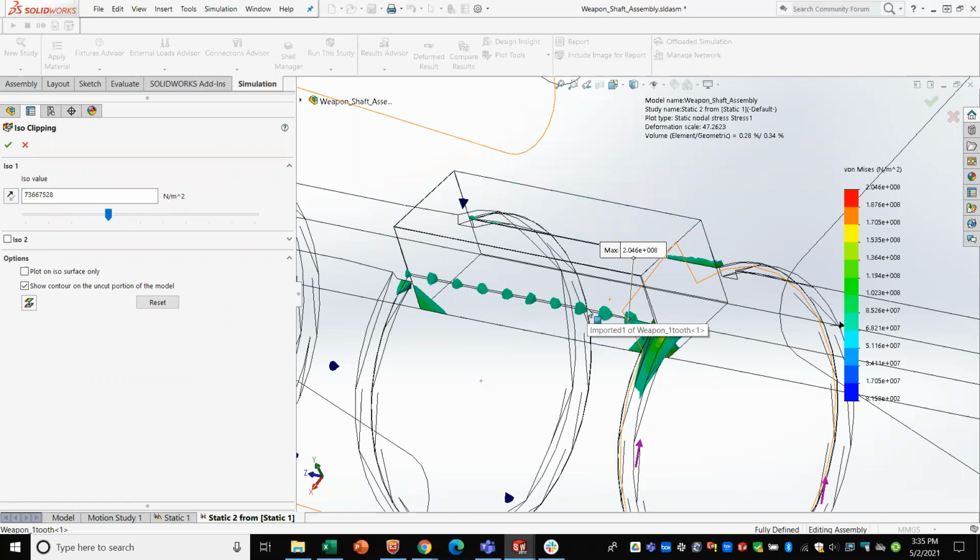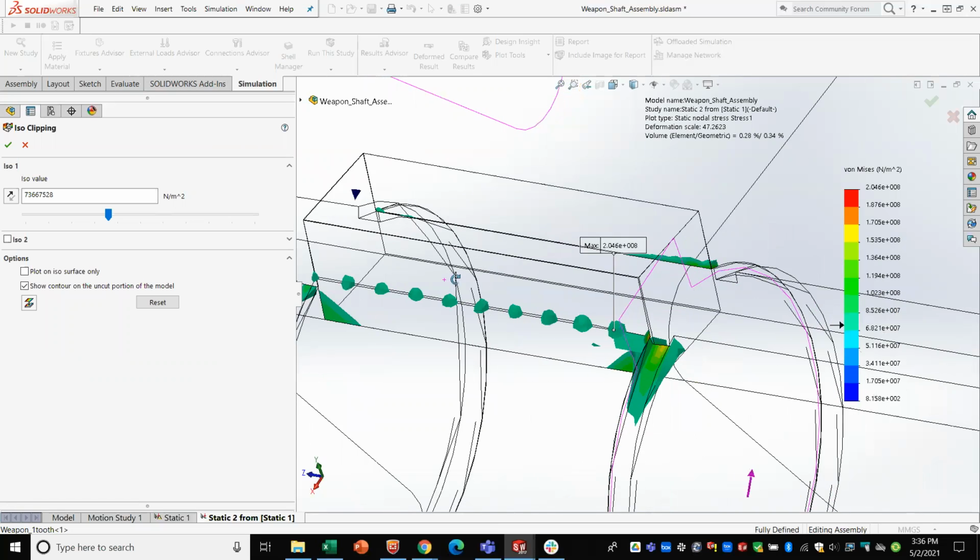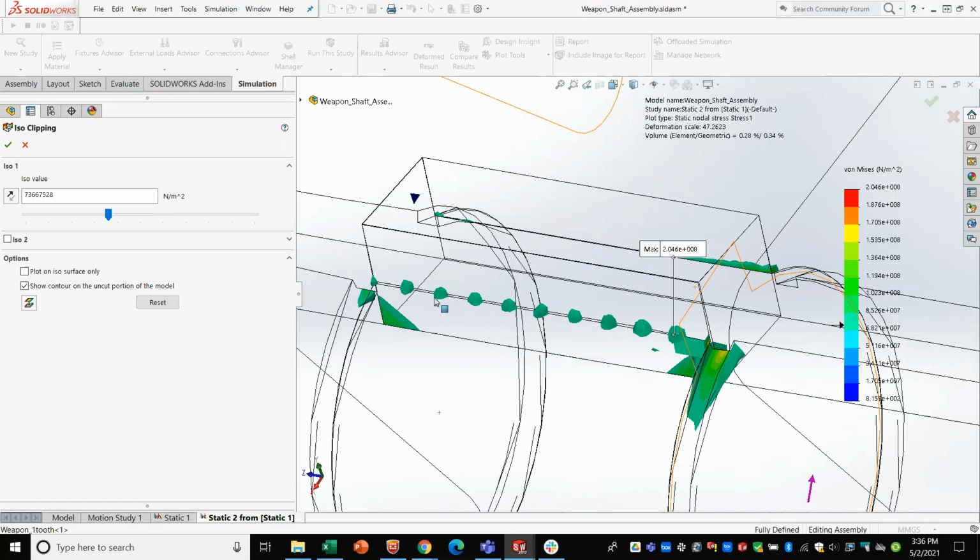And those individual points of high stress are caused by basically the no penetration contact not being applied evenly between dissimilar triangles. So there's a triangle that's really small on one side and a triangle that's really big on the other mating part, and it's trying to apply all the force from one triangle onto the other one, and you get areas of very high stress concentration at the boundaries. So this is one of the things you have to worry about when you do no penetration contact. You'll get effects like this.